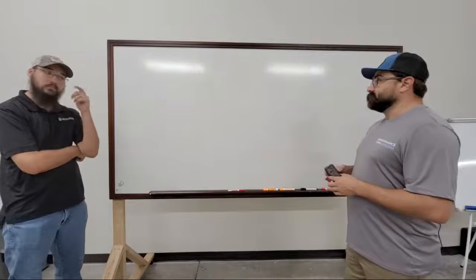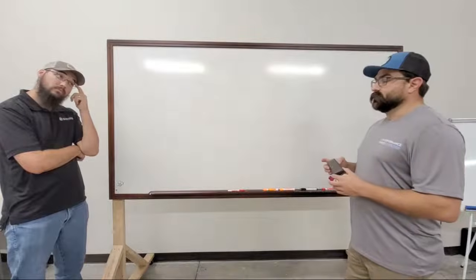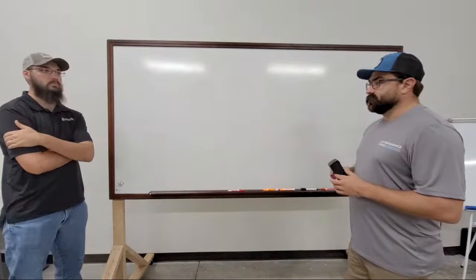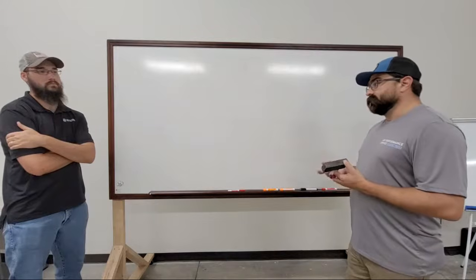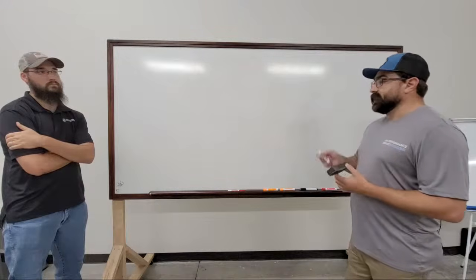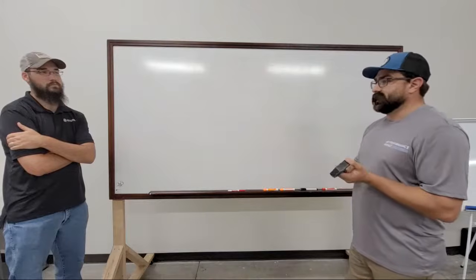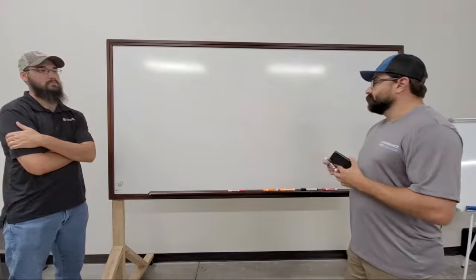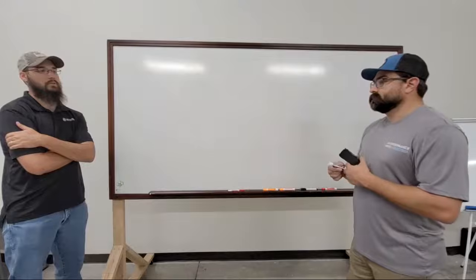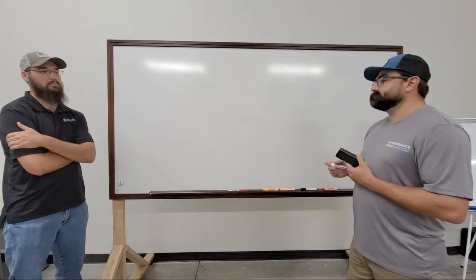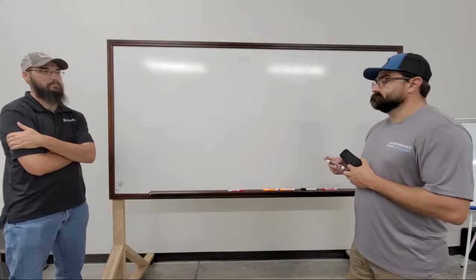Typically, we don't like to do two controllers; we'll do one controller with two actuators, which is the best way to do it. Some of the dual ducts actually have a single actuator, where the damper is joined together. So those are nice. That goes back to the multi-zone concept.